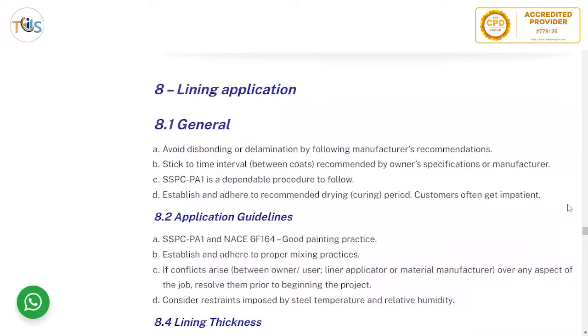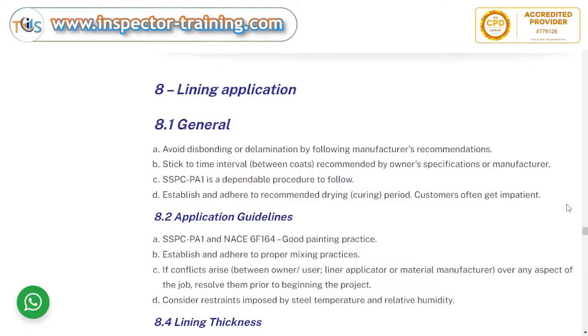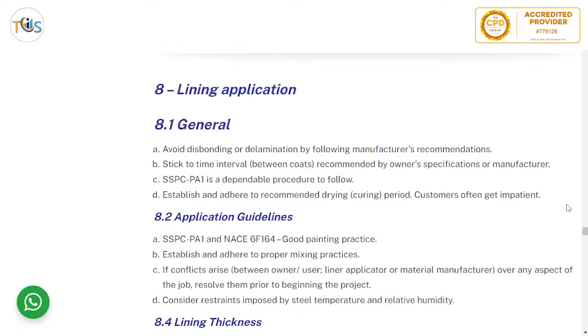Lining application, 8. Avoid debonding or delamination by following the manufacturer's recommendation. Stick to the time interval between coats recommended by the owner's specification or manufacturer. Always follow the manufacturer's specification. That is true in every project.